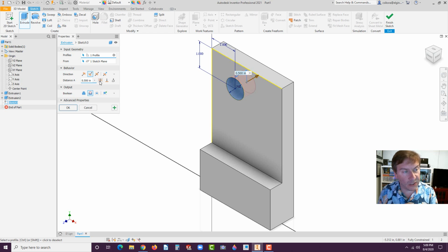If you left this thickness at 0.5, then you change the main bulk of the rectangle thickness to 0.75, you'd have to go back to this feature too and edit it and change it. And you can have a whole array of features that were done that way. So there's something called design intent. And design intent crosses over all CAD systems. It's your plan on how you want things to update if changes do occur.